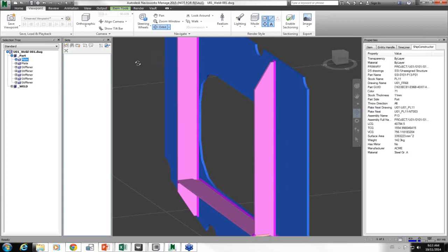So, for example, right now I'm looking at my weld types. Now, as I saved that drawing, it was back with the colorization of the welds based on weld standard. So I might use this for some walkthroughs, maybe for the work that was modeled during the day. Not necessarily quite as focused, perhaps just walk through, take a look at the welds that have been done. And again, by color, now I can tell pretty quickly, is this sort of what I'm expecting in this place? And if something looks a little out of place, then I can now focus on it.